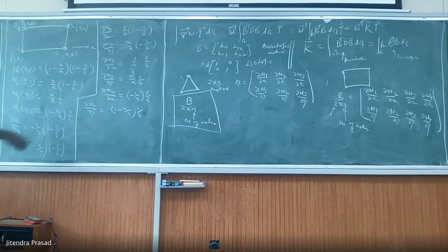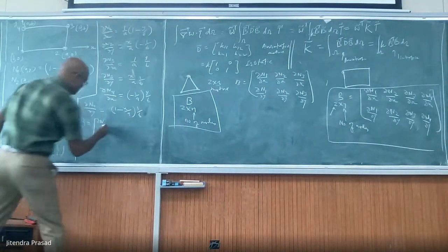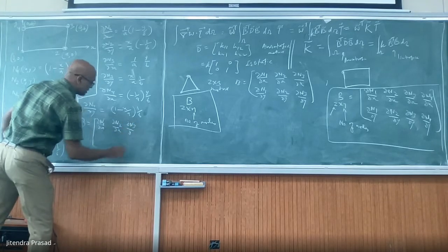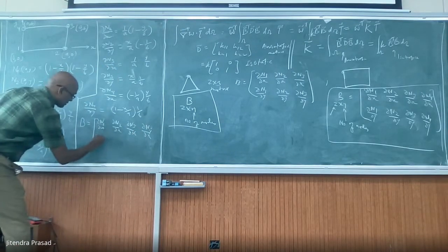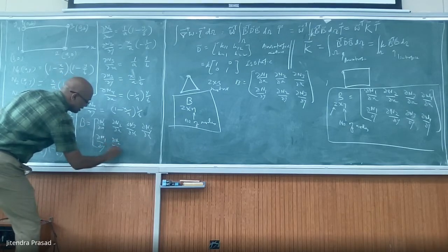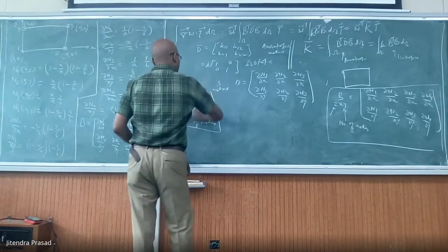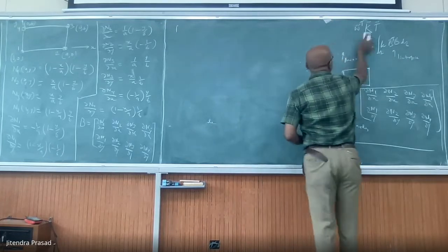And the rest, you know how we can compose B. B will be equal to, so if I leave it there, B is like this. We just repeat it here for continuity. So we have del N1 del x, del N2 del x, del N3 del x, del N4 del x, and then del N1 del y, del N2 del y, del N3 del y, del N4 del y. So we have this, and from that we can easily find out k11, k12, and so on. So a few we can compose basically.